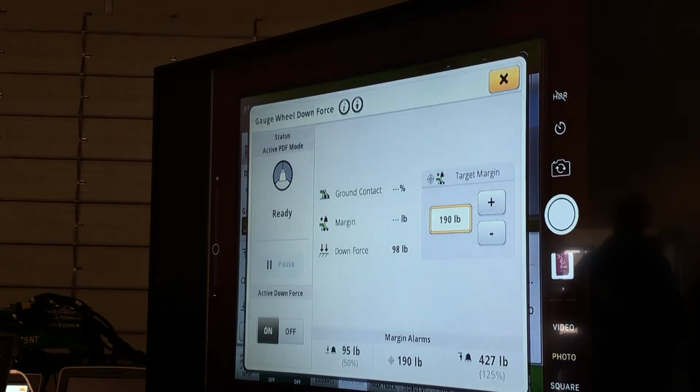This can be used as a good diagnostic tool. For some reason, if you're not getting that second piece of the pie and your tractor's moving, we need to see, okay, am I getting tractor speed, or is my wheel motion sensor working? Those are a couple things that we can start to think about.